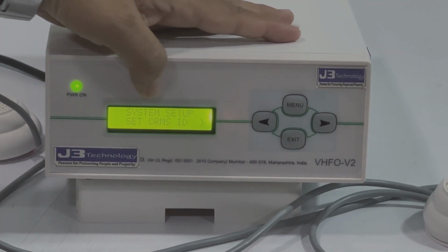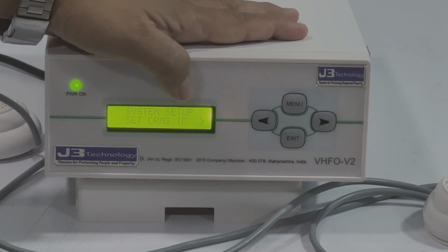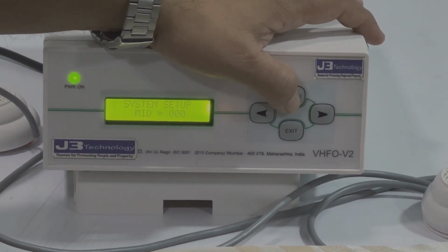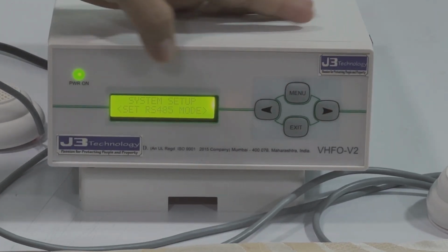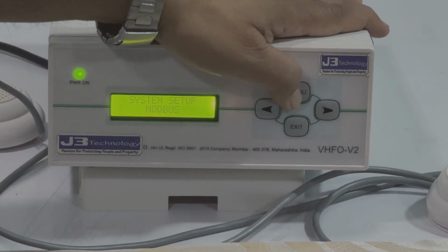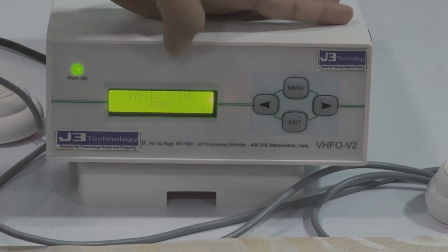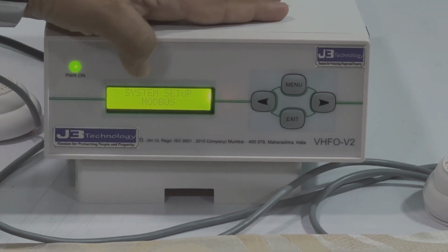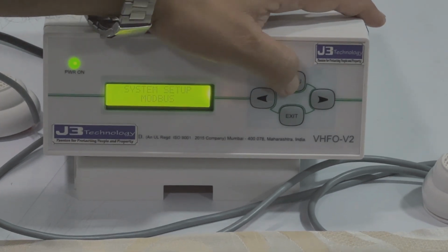You can see the set CRM software. If you are using CRM software, you have to give an ID to each and every panel, like 1, 2, 3, 4. If you are using Modbus, then you have to go to the RS setting for RS485. Just press enter. Now it is in Modbus or CRMS. These two options will be there. Now which one do you want to use? If you want to use Modbus, just click on Modbus. Just press the menu button.